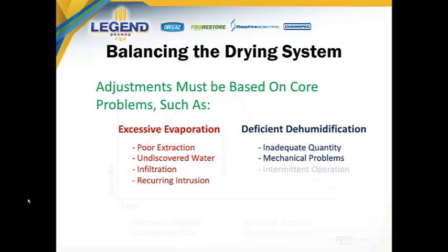In addition to that, what if the dehumidifier is not operating properly? You installed the dehumidifier and got it up and running, but then the homeowner decided that it was a little too loud, so they just turned it off. Doesn't matter if you add another dehumidifier, all you're doing is giving them another power button to push when you walk away. So adding a dehumidifier again here would not be the appropriate fix.